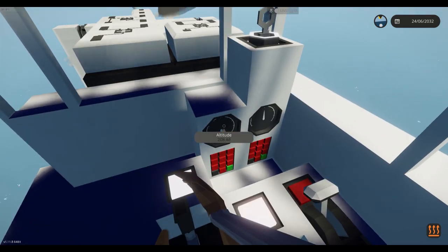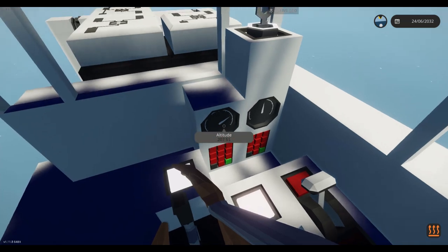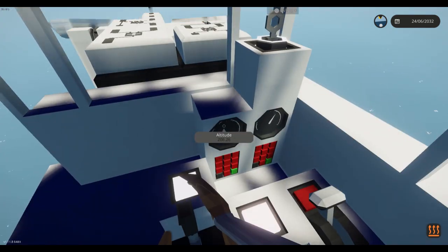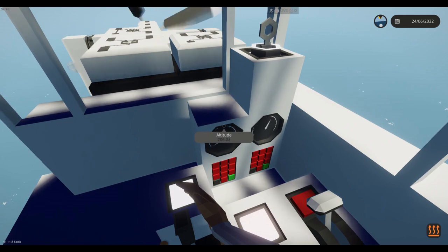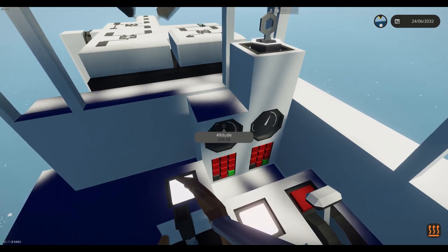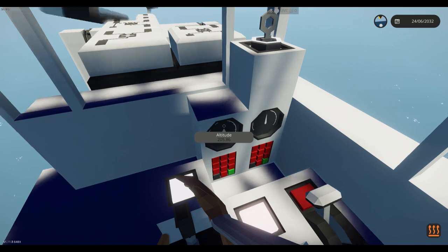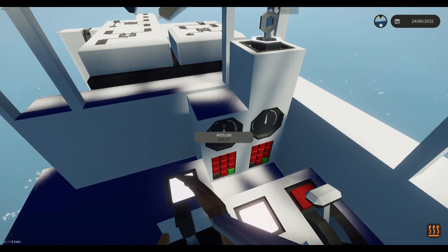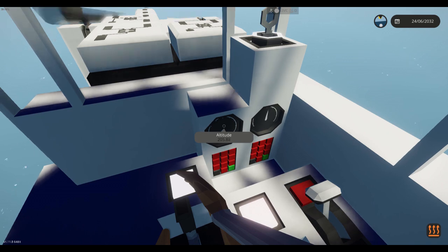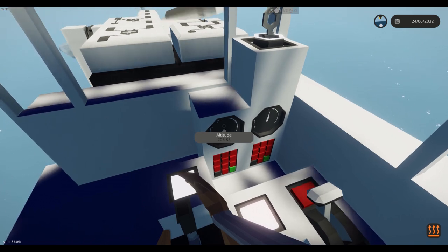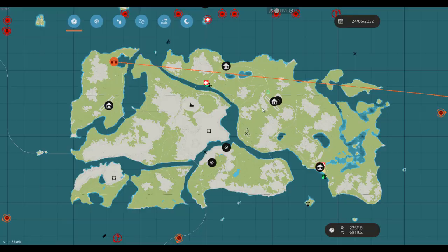So it was doing 5 more earlier. So let's see what happens here. We want it to go to 200. And let's see where it stays at. Yeah, it looks like 205. Looks like it's going to stay about 5 values higher than normal. It's starting to slow down. Now what we can do is we can try changing the integral value, which we will do now. Yeah, it's hanging out about 5, so we'll do a couple of things.